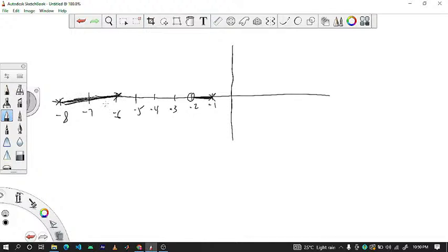Now we know that there was a centroid here at negative 6.5. So our asymptotes move along the centroid. The first asymptote goes to angle 90. The second asymptote comes to angle 270. So we measure the angles this way, 90 and 270. I have it like this.